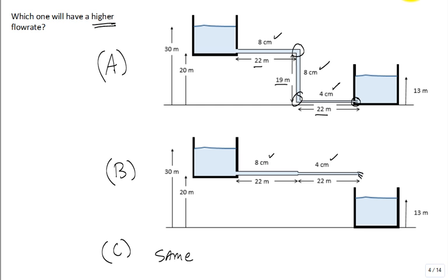All right, now I'm going to outline a little bit of the strategy we had. We had rho g delta z equal to some sort of one, we wanted to come out of the end of the pipe fast, plus some loss coefficients for the minor losses, and then the f L over D's for the majors, and then we had the dynamic pressure 1/2 rho V squared.